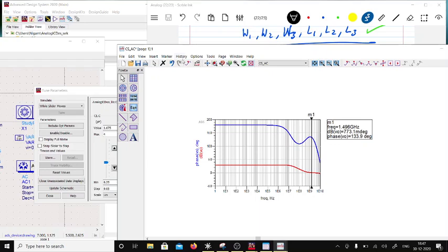Marker new. So you see, this is 180. The first corner has now gone to 77 kilohertz. So what is the first corner? Let's put it on the other axis. Marker new over here. This is a gain of 29, then a gain of 26.